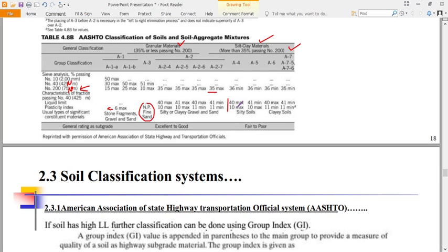Is that okay? The plasticity index, if I can remember, is equal to liquid limit minus the plastic limit. It is the measure of the amount of water you require for a material to move from being a plastic material to a boundary at which it will just flow under its own weight. Is that okay? So the more water the material can take, the weaker it becomes. If you remember our equation, effective stress is equal to total stress minus water pressure. So the more water a material can carry, the bigger the PI, the weaker the material will be. Is that okay?